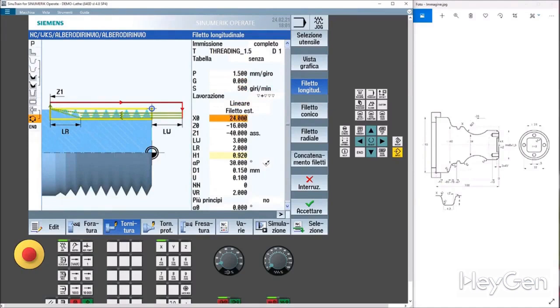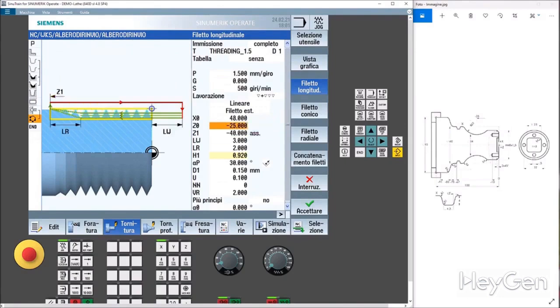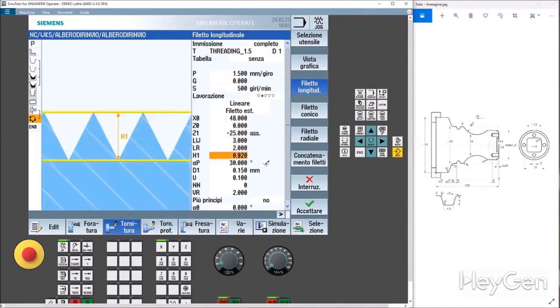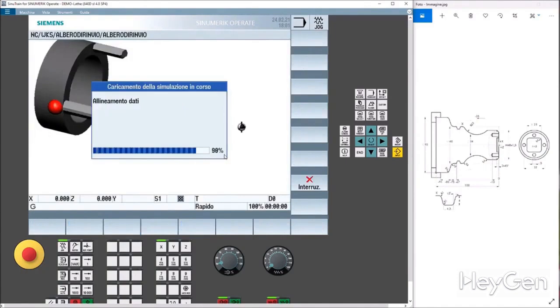Let's start by carefully giving it mainly our machining points. So, 48, length. In this case, we have to estimate a bit. Otherwise, we could go read the program because you see that it doesn't show it here. So we set it to -25 and then we'll see if we need to extend it. Sorry, this is the initial Z, and this is the length, Z25. Safety distance, exit distance, thread depth, attack angle, increment. Excess material for the finishing pass. We accept it, and we're good to go.